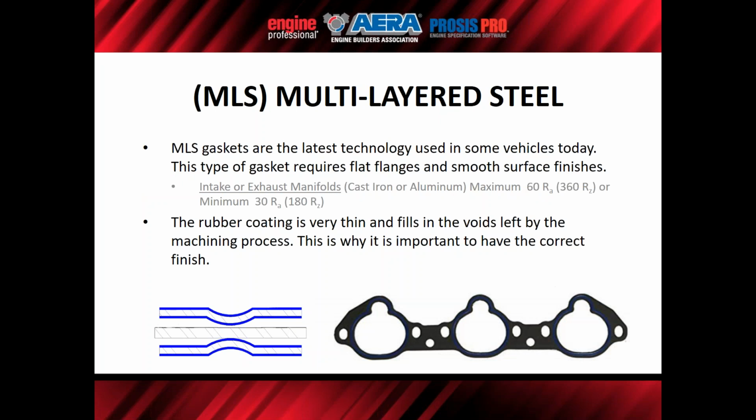All right. Multi-layered steel is probably the newest technology for intake manifold sealing. It's not very common. It's not used everywhere, but it's there. If you're used to an MLS head gasket, it's the same concept. You have multiple layers. So here's an example of a rubber coated layer here with an emboss in it. Then you have this distance layer in the middle, and then you have the same thing inverted here with another rubber